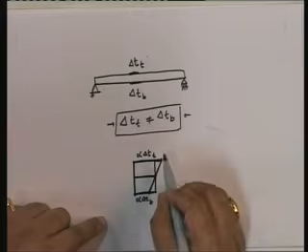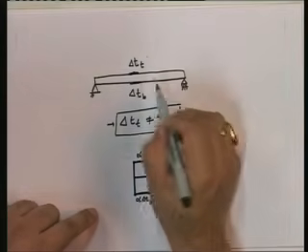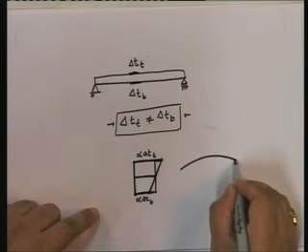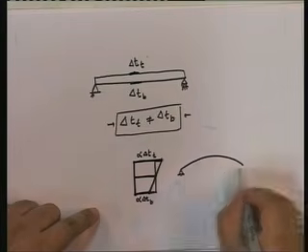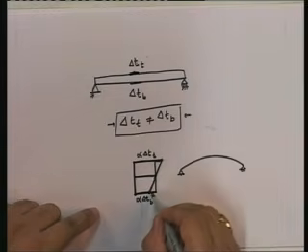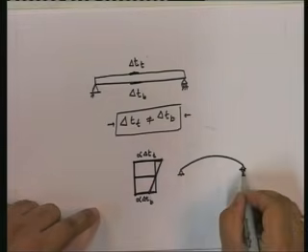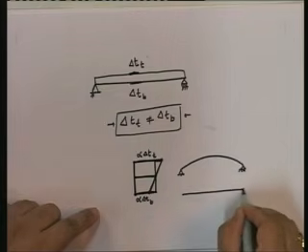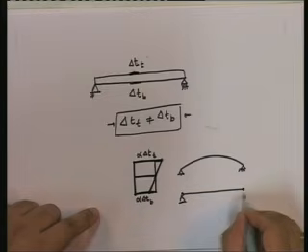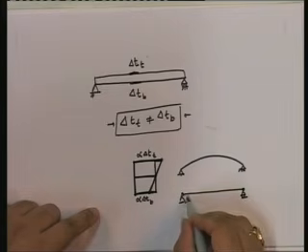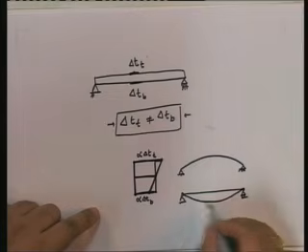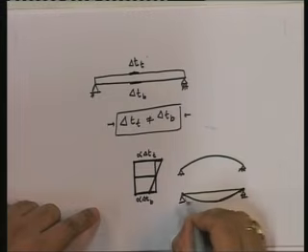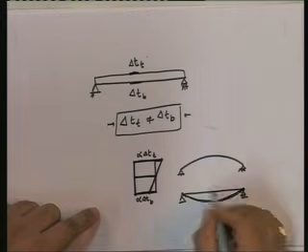If there is a flexure, what is going to happen? If you look at this, if delta T top was higher than delta T bottom, this is how the member would go, in flexure. The bottom would go in compression, the top in tension. If the inside temperature was higher than the outside temperature, then the member would deform in this fashion.